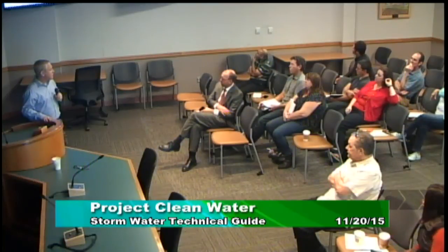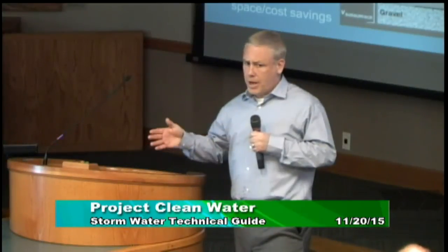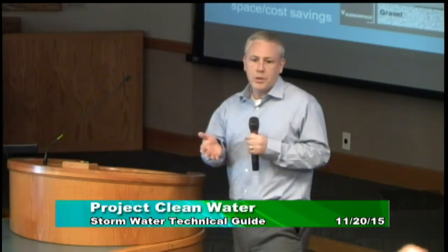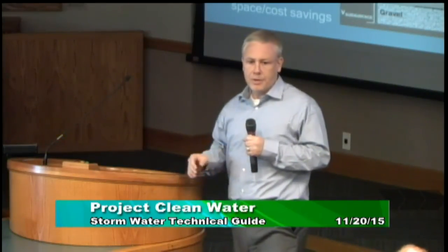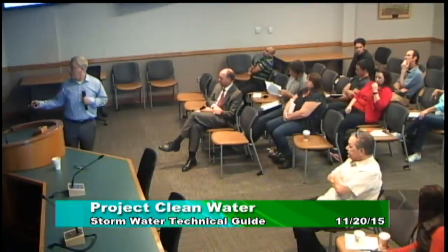If the bioretention were designed at the same size with a flow control orifice, it would infiltrate more water. But if we're aiming for the same performance, what we can do is reduce the dimensions of the bioretention. Like Dan said, 20%, often more than 20%. Okay.